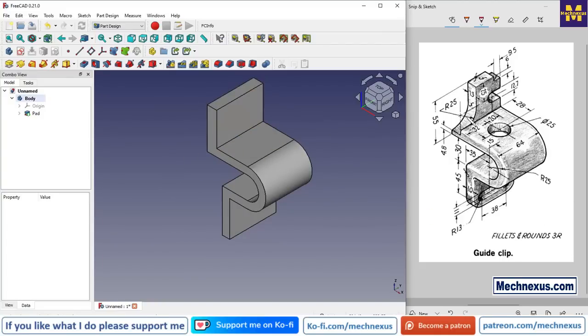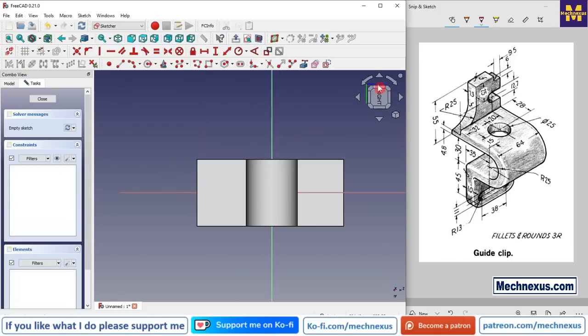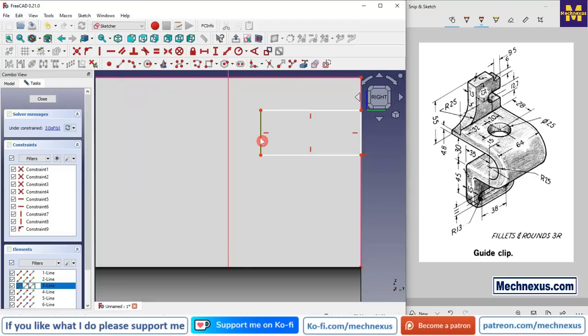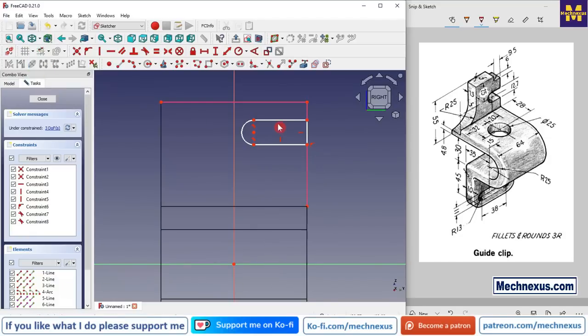Now our next feature is to create this slot. So we will select the face and click on the sketch. We will rotate our model and we will project these two edges and click on the rectangle, and here we will delete this line and click on the 3-point arc and create an arc. And now we will add the tangency. Now we will switch to the wireframe for better visibility.